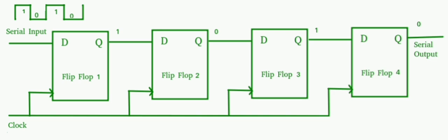When the signal changes its value, that determines how fast the logic system can operate. Delay time TPD equals TPHL plus TPLH by 2 nanoseconds. TPLH means delay time in going from low to high logic state. TPHL is delay time in going from high to low logic state. The delay times are measured between the 50% points on the input and output transitions.